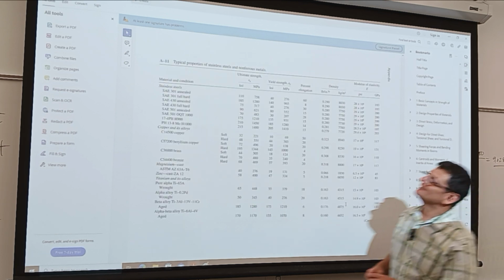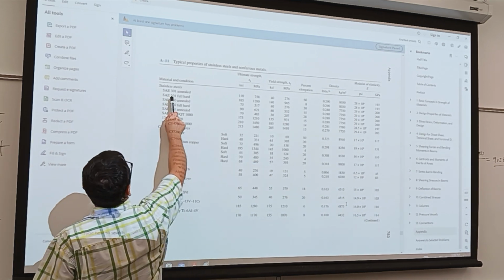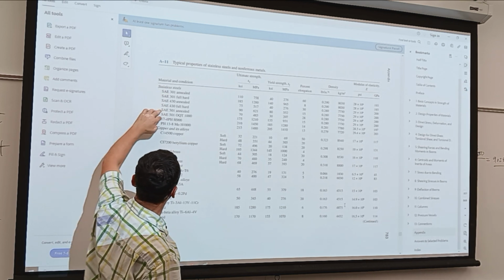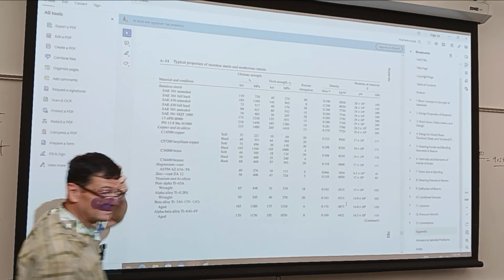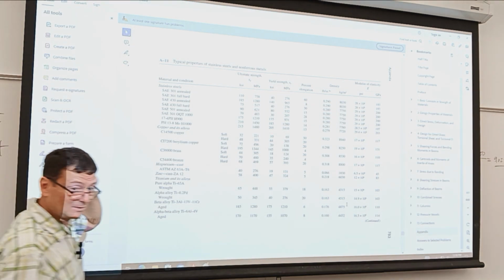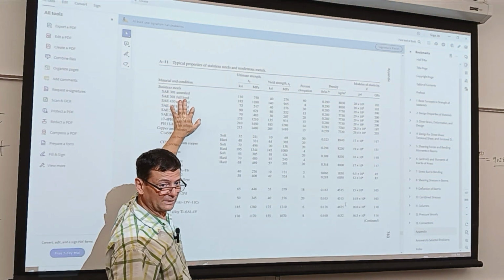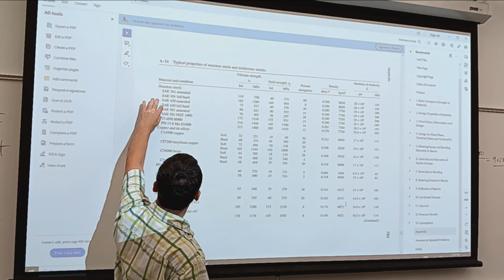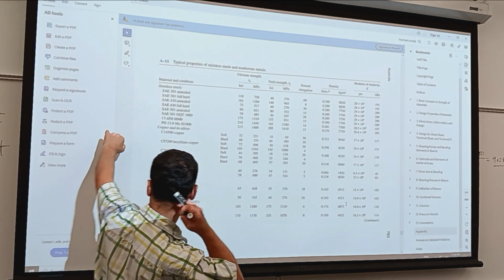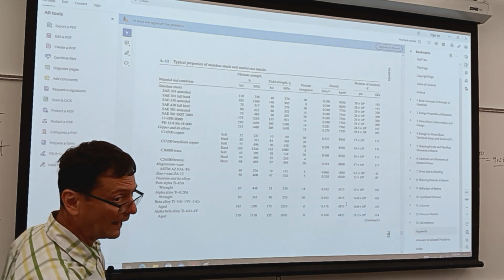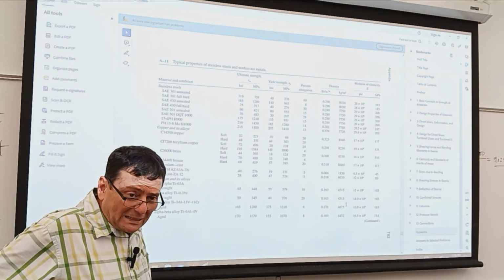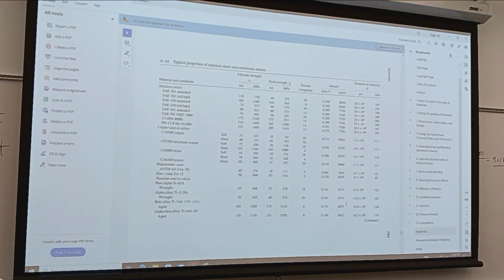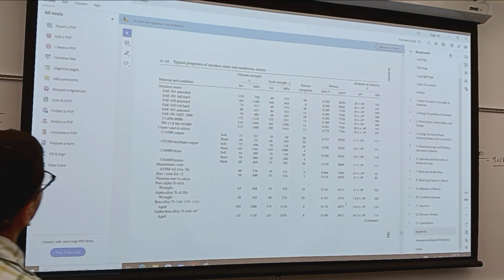These are stainless steels. There are various types of stainless steels. By the way, SAE, the Society of Automotive Engineers, is now in charge of designation for various steel materials. They need various steel grades to satisfy their strength requirement and also cost. There's a type of high strength, low alloy steels. Alloying elements make the steel expensive. Nickel is one expensive material, if you wonder. Chromium is less expensive.